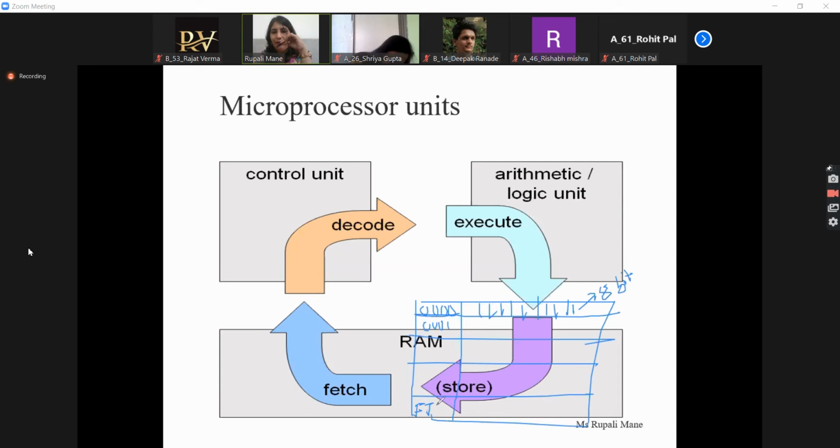Why am I saying F F F? Because we can interface 64 kilobytes of memory. That's why. Okay, sorry, not 64 kilobytes, it's 1 mega. Because the address bus is how many bits? 20. So here 0, then here 0 0 0 1, then here F F F. Okay, so what is that? That I'll explain. Just keep in mind this number.